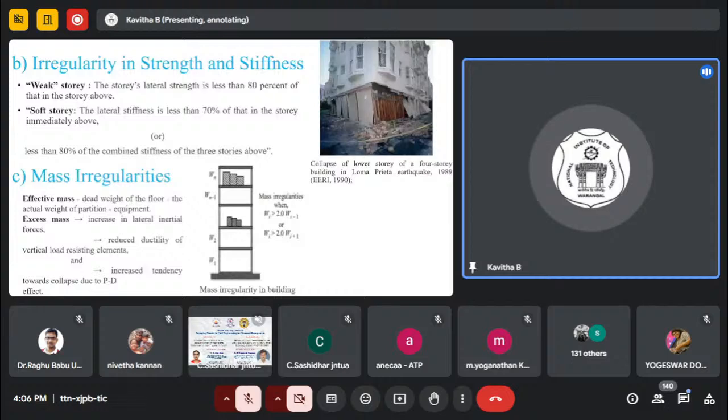If these things are taken care of, the design and detailing stage will be smoother and easier. Okay, so these are very basic things. One has to avoid soft stories. Definitions are there in the code, but basically the bottommost floor is now being left open for parking, and open stories for some auditorium purpose. These have to be avoided unless really needed, because that lowermost floor is the one that takes the force directly and there is tension in the system.